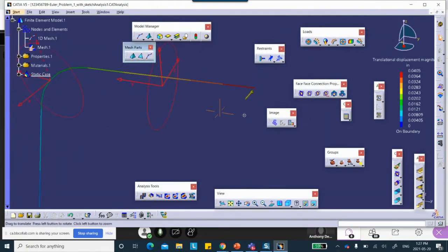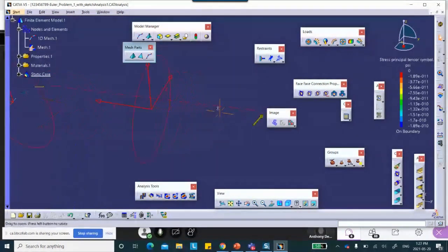Okay, good. Now, the bad news is that CATIA's beam bending models do not give stresses. There we are. You cannot plot von Mises stress. You can plot something called principal stress right there. See, I open this up with the displacement. The second item is principal stress. The only unfortunate thing, you know what a principal stress is? The only unfortunate thing is that it gives you the principal stress as the axial stress. Totally useless.